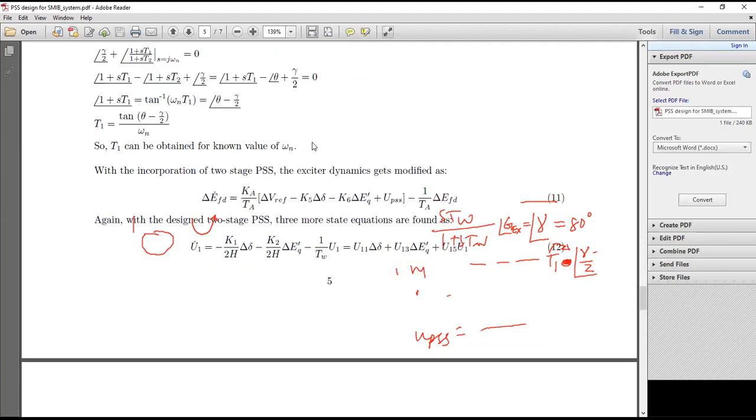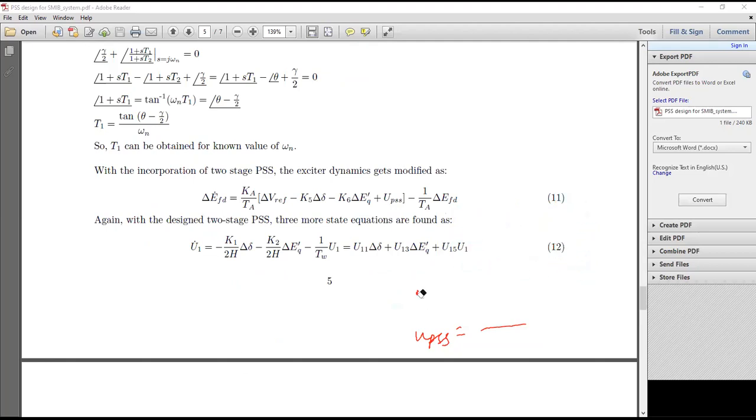Again, take TW equal to any value between 5 to 10 seconds, comparatively larger than the time constants associated with your compensator blocks, that is T1 up to T4, whatever values you are using. At this point, you would know T1 up to T4, so you take TW accordingly, let's say 5 times T1 or something like that.